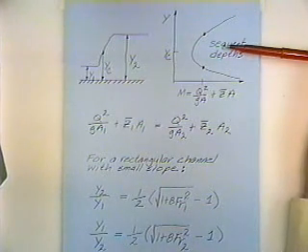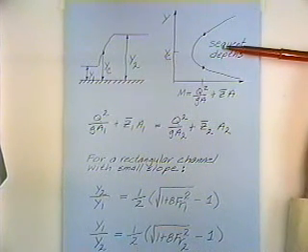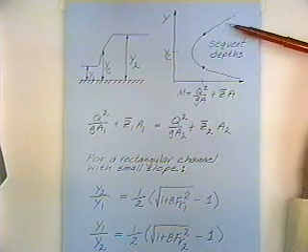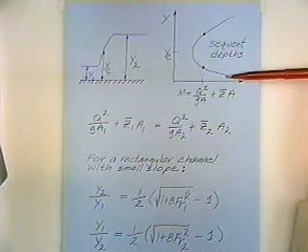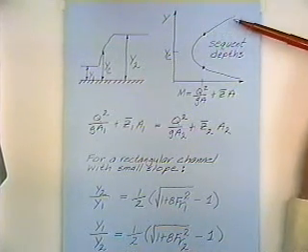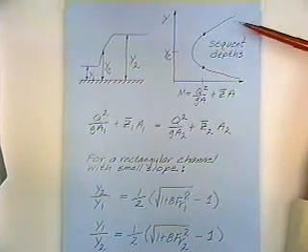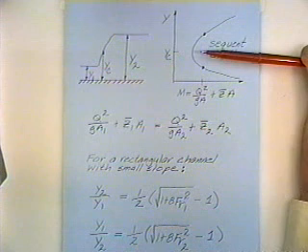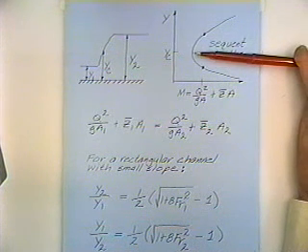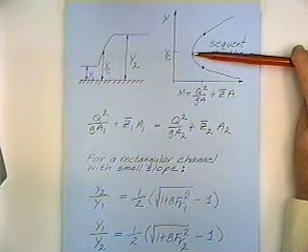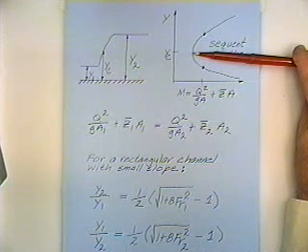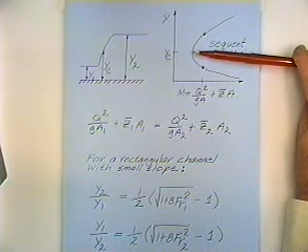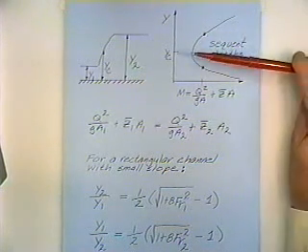Before, we looked at a diagram like this in which we were looking at specific energy. And specific momentum is sort of the same shape. The shape's a little bit different, but it's the same general analogous concept. The critical flow, by definition, is the condition in which the specific momentum is a minimum. Before we said the specific energy is a minimum. Both conditions hold true.